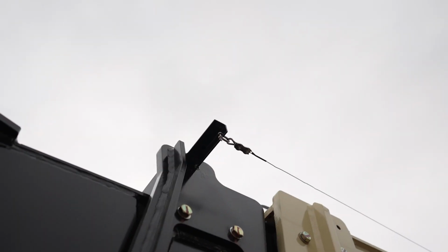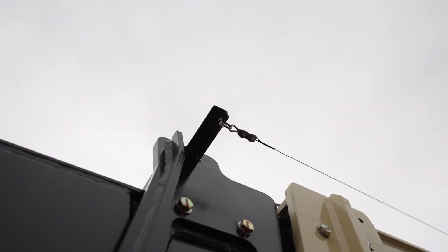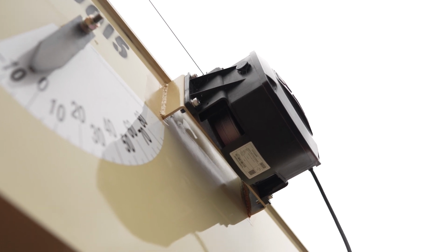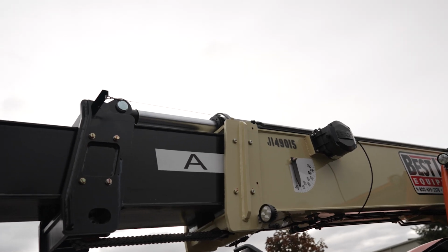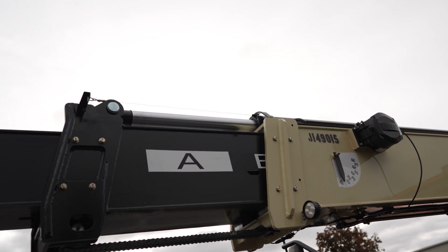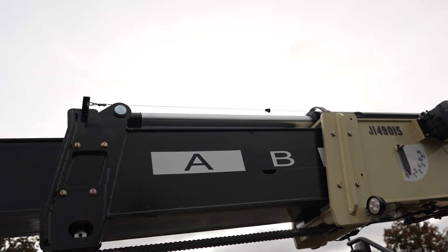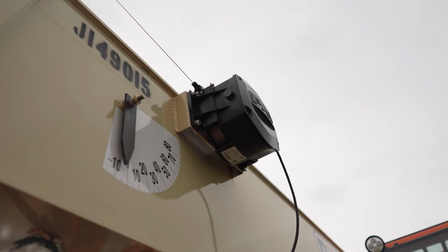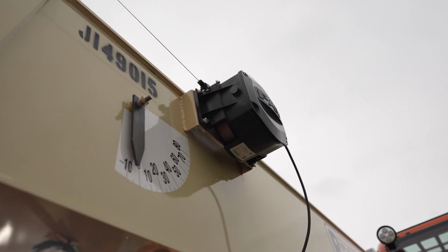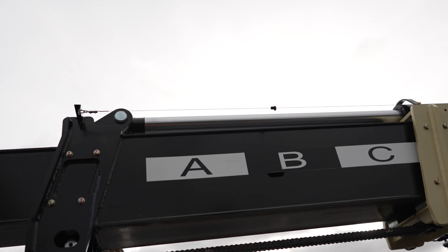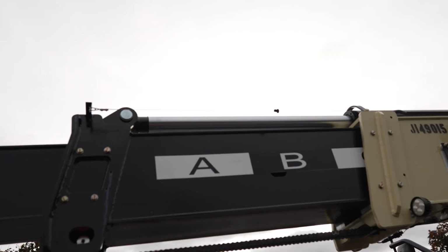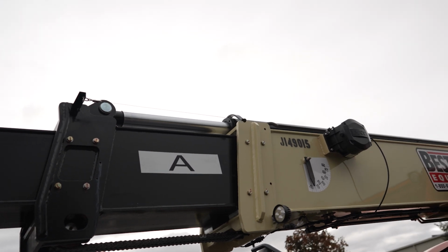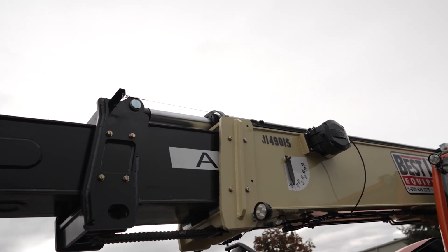The cable reel includes a length cable on a spring-loaded rotating drum that is mounted to the first section of the boom. The end of the cable is attached to a telescoping section of the boom and measures the rotation of the drum through an internal length potentiometer. An internal angle sensor measures the orientation of the cable reel and boom. As shown in our example, the cable reel can be mounted externally on the boom, or alternatively, a smaller cable reel can be mounted internally within the boom.